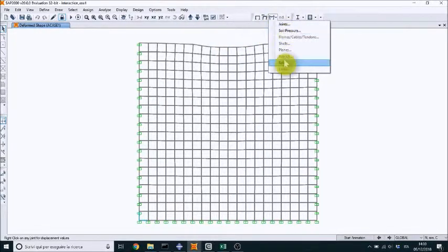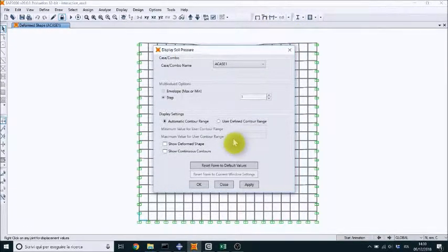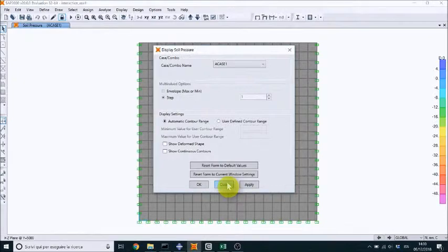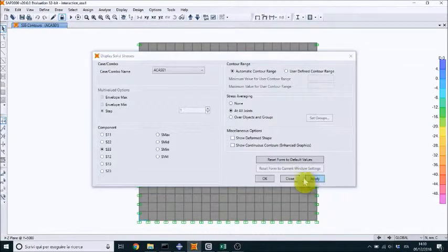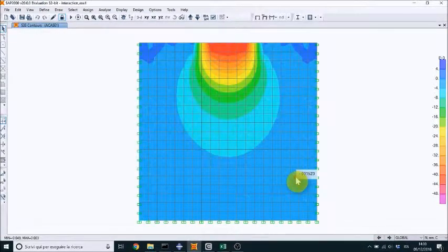You can check with the theoretical equations. We can see also the stresses distribution. That is a really interesting case because you can see that it is completely different from the previous one. And this is the classical solution of Boussinesq, and you can check it by the theoretical formula, by checking in the middle of the soil and in the other parts. You can also try to modify these boundary conditions to see if there are some differences in the displacement or not.